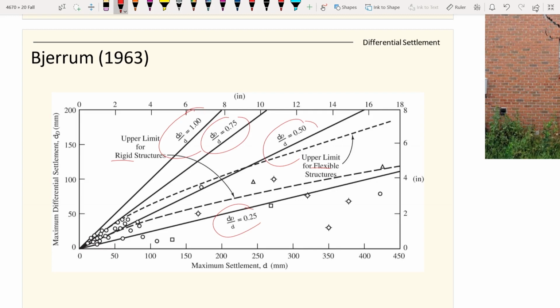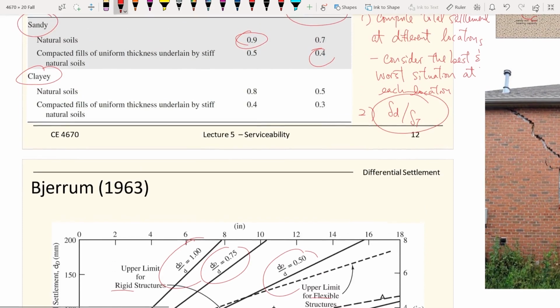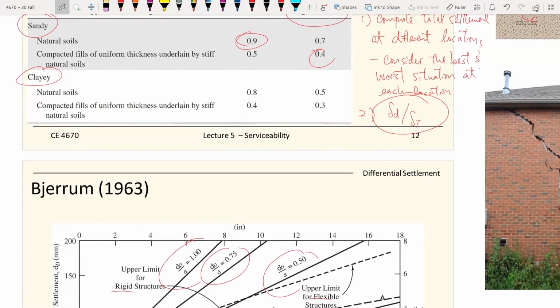Very likely you need to discuss with the structural engineers what tolerance the structure can take. The structure size may have some code or reference they pass to the geotech, and from there we can know the differential settlements. So this is kind of a back-work analysis, to find out how much settlement the soils can take, knowing the design criteria from the structural side in the first place.